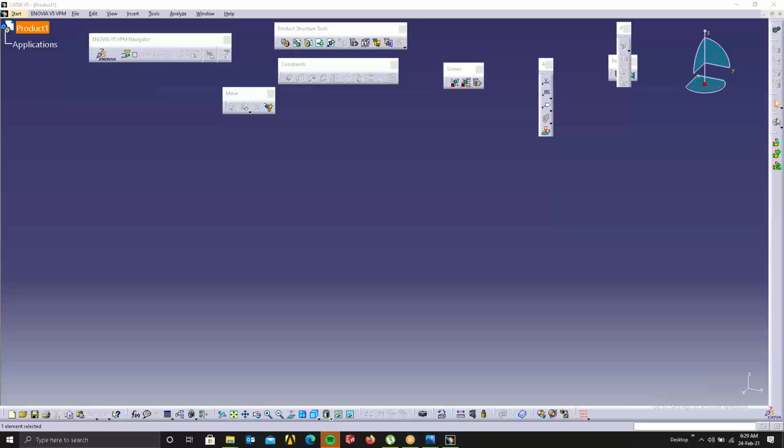For that, what we can do is use a filler. We'll use a slightly thicker filler. If you're using a 0.1 filler, we will use a 0.2 filler. Whatever the fluctuation is, it will be around 0.02 to 0.05 in that range. So if you're using a 0.2 mm filler, that will subdue it, right?